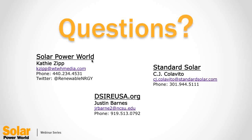I've found in our experience that most residential applications do not have time of use rates available, that they're under a pretty standard residential tariff that may or may not be seasonal from summer and winter. So I would see it to be a little bit unusual to see time of use for residential, but if it is available and you're allowed to select it, generally that's an advantage, but it's highly dependent on the way the tariff is structured and then also the type of PV system design. Again, if it was primarily east-facing, you would probably expect more of your generation to favor the morning rather than the afternoon, and that may or may not sync with the peak times.